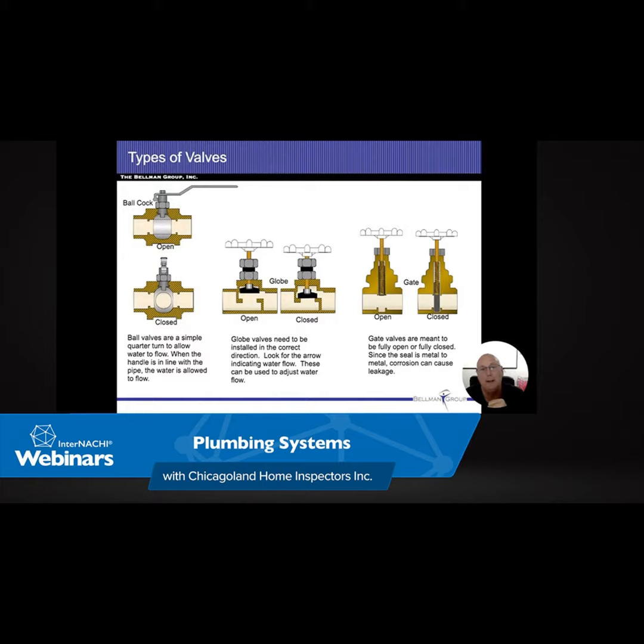And I don't want to give my client hope, saying, oh, I don't have a lead problem here because it came back negative. Well, that may not be true. The water might have only been sitting there for a minute or two, or just passed through it, in which case we're not going to get any sort of lead readings from it, just because the water hasn't been there. It's got to leach into the water overnight. So I'd rather people treat it as if it is a problem.